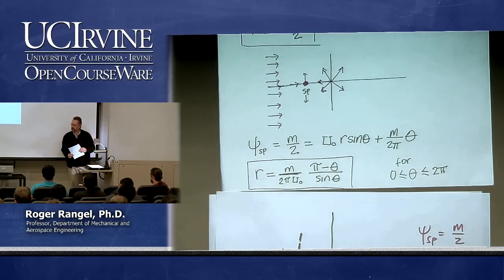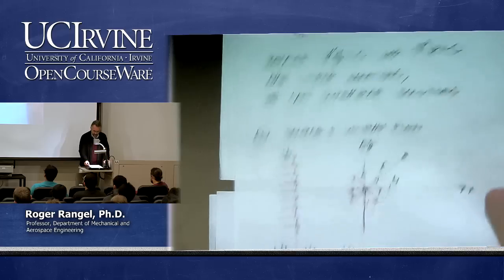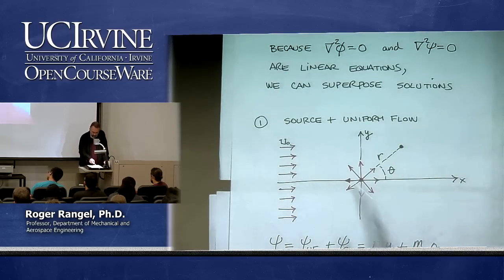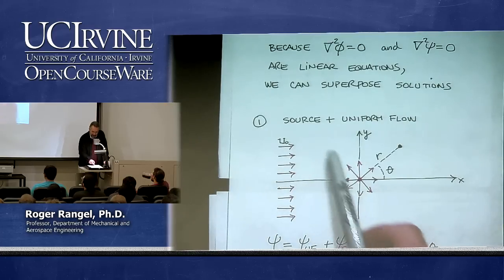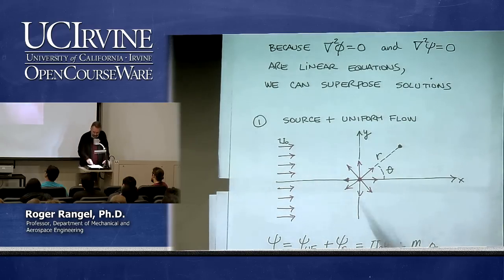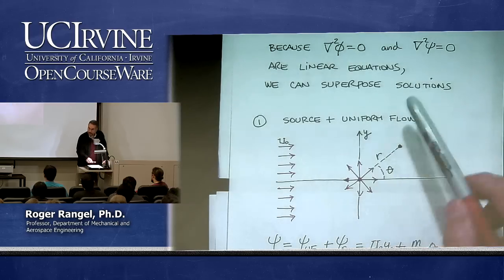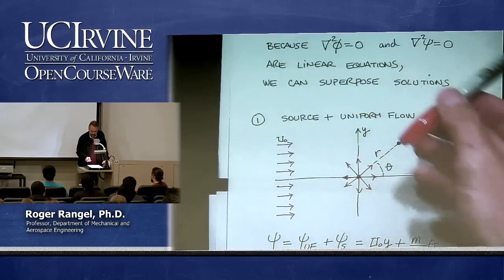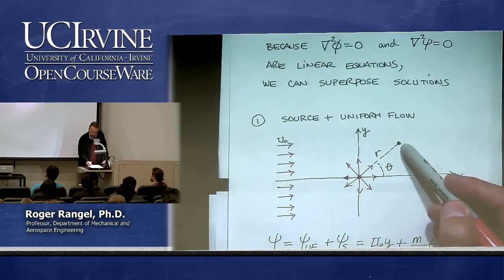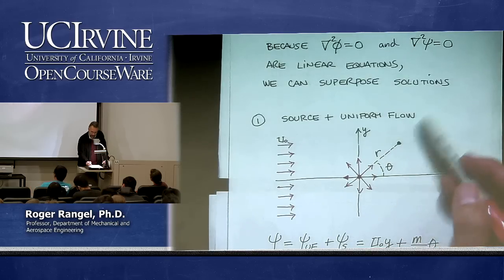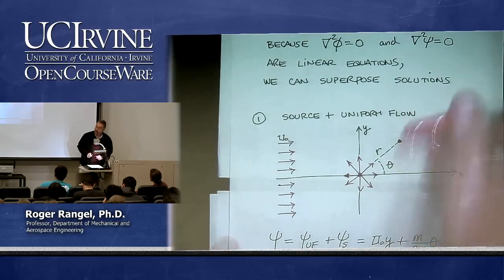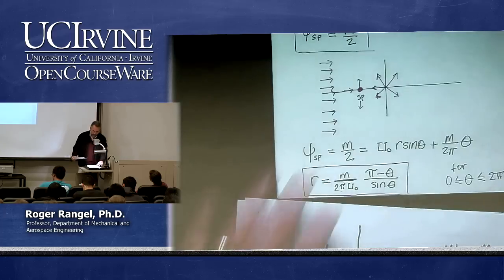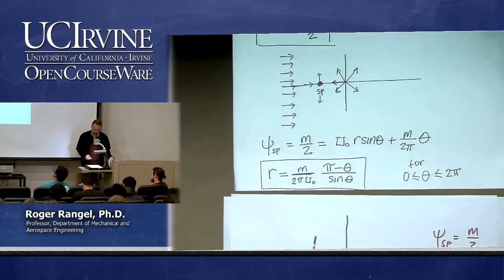That is not too surprising, because if you look at this, and you try to find the velocity somewhere here, it's the addition of the uniform flow plus that. If you do the vectors right, you find that indeed it'll be up and tilted to the right. It's a lot easier to see on a point like here in the back, because I have the source going that way and the uniform flow going to the right, so that's clear that it will give me some vector that way. But what does the whole line look like if I plot this?